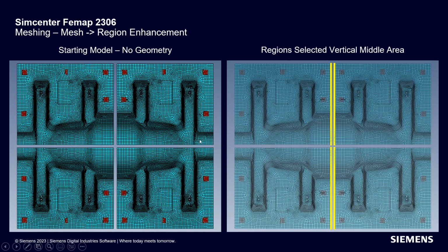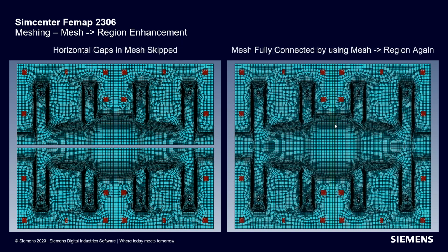So here's a quick example. If you start with this model that's 4 different sections, it looks like probably just rotated and reflected. You can then join them if you just select the elements on one side and the other, or maybe just all at once, and then it'll zip them up and create new elements to join them together. Again, you have to have the same number of nodes and elements on either side, but not aligned numbering, if that makes sense. And then to zip the center up, the same command was just used with the matching nodes and elements. So that's pretty neat. That'll save some time in the future.